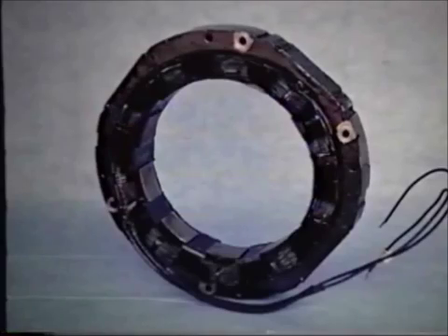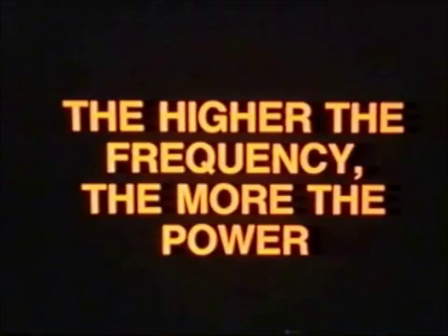As the AC output current of a brushless exciter is rectified to DC, there is no need to limit its frequency to 50 or 60 Hertz. In fact, most manufacturers of 4-pole 60 Hertz alternators construct the exciter field with 6 or 8 poles producing 90 or 120 Hertz to give a smoother DC output. And to take advantage of the fact that the higher the frequency, the more power that can be taken from a given volume of active material.